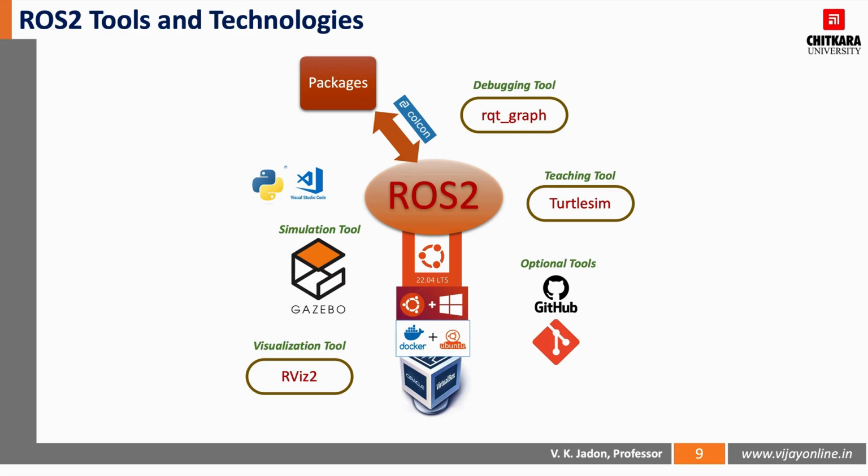To help you get familiar with ROS2 concepts early on, a very good package is available in ROS2, and that is TurtleSim. TurtleSim is a simple graphical 2D simulator to be precise. It is a fun, beginner-friendly tool that lets you control a virtual turtle using ROS2 nodes and topics. Finally, we will install the ROS2 CLI tool, that is the command line interface, to interact with the system from the terminal. These command line tools help to monitor nodes, topics, services, and actions, making it easy to control and debug.